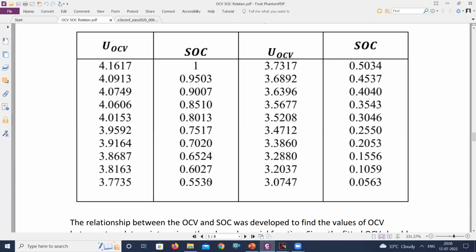So a maximum of 0.1 variation we should have in the case of NMC chemistry. And in NCA chemistry, that would be revolving around 3.6 volt. Also, a few manufacturers make cells at, like, if it is the Panasonic cell you purchase, it will come at 3.67 volt. An LG cell you purchase will come at 3.67 volt.